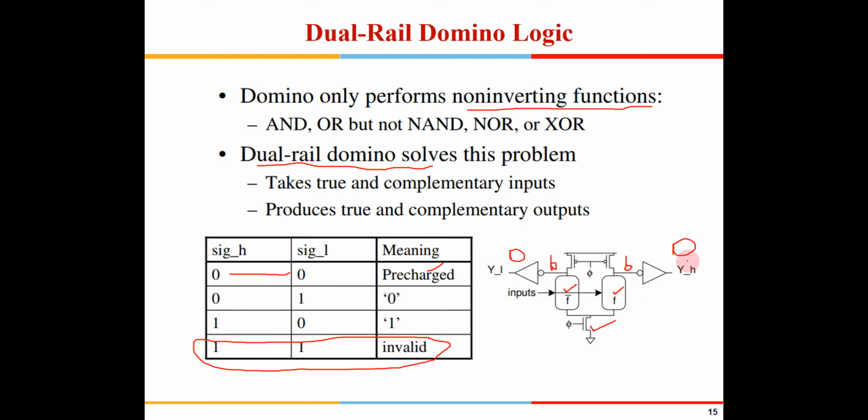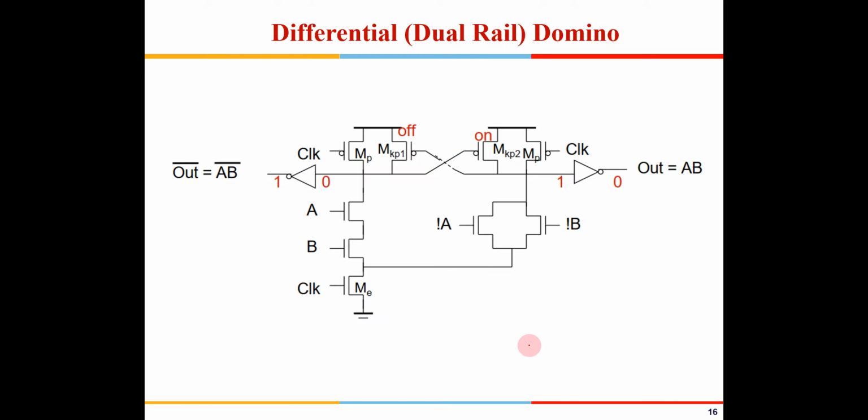Now if Y and Y bar are available, it becomes easy, because when you make a K map or anything, you might require, you have generated one set of functions, then again you are using those functions in another K map, so you might require F and F bar there also, right? Y and Y bar also there, right? And in domino logic, if it doesn't give Y bar, then it becomes a problem. So you can use this in a dual rail kind of thing to generate both Y and Y bar, which can be used in the next stage. Is it okay with all of you? Yeah.